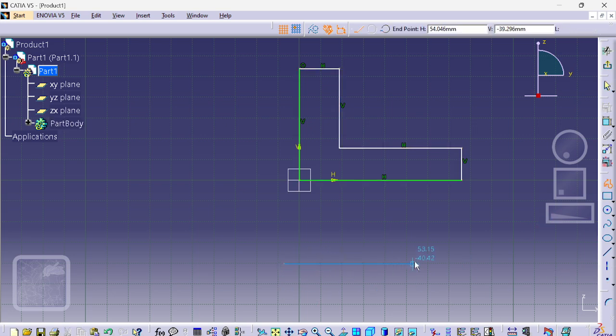See the difference: if I create one line and hold it, it will create a radius line. So don't move it. Just give the direction, and when you want to stop, leave your mouse, left click again and change the direction. In that way you can complete it. Try it. Just try it.